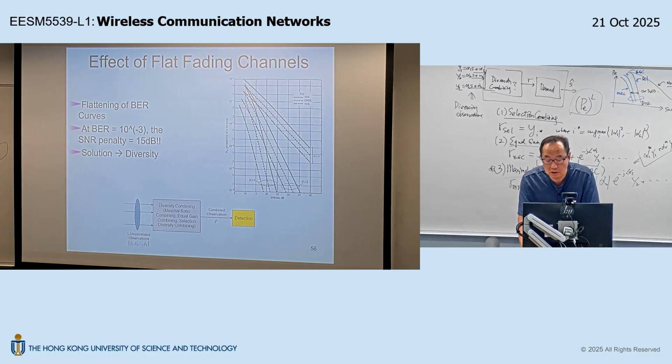So then the next step is, how do you create 2 diversity observations? As we study, right? It can be coming from time, frequency, or spatial, right? But at that time, this was a startup, right? And time diversity and frequency diversity have the spatial efficiency penalty of 50%. This is not good, right? Moreover, if you want to engage in time and frequency diversity, you need to change the standard. You need to change the Wi-Fi standard. So this is not suitable for a startup, okay?